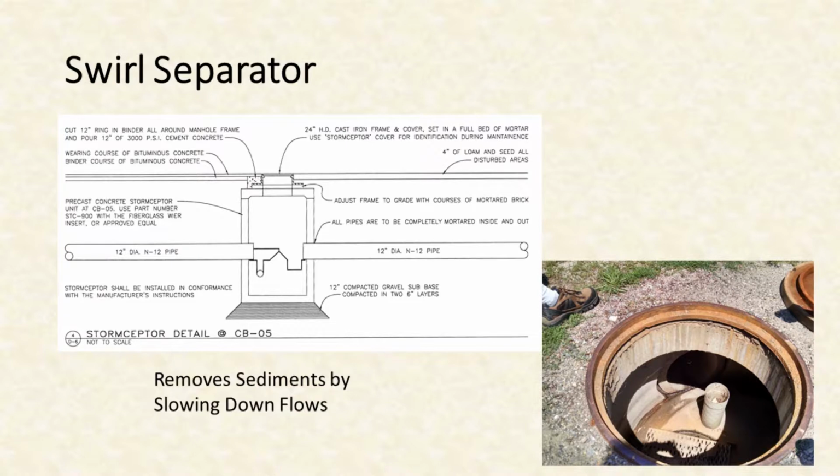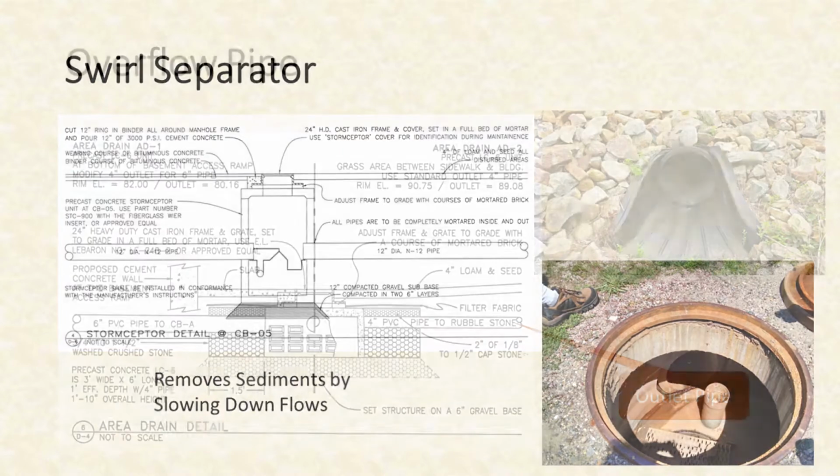These prefabricated structures are typically used in 2 different ways. The first as a pre-treatment device to remove sediment prior to discharging into a downstream stormwater treatment system. The second, in a retrofit situation where treatment options are limited. In coastal waters such as Buzzards Bay, research has indicated that these types of structures are not very effective in removing pollutants such as bacteria and nitrogen.